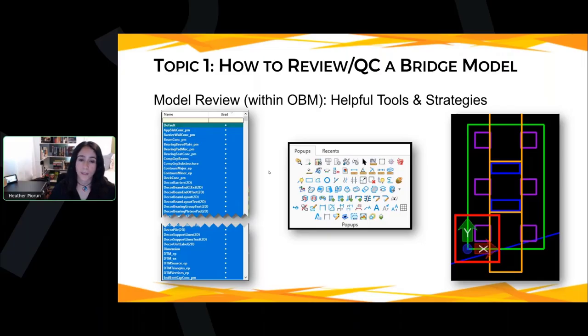And Steve could probably talk for 20 minutes about this, but I'll just give the short version, which is the tools are grouped together to make sense, right? You've got your Explorer, your FDOT create file up here, your design file settings, some very commonly used tools that may require 3 clicks through another method, but here you can access them immediately.